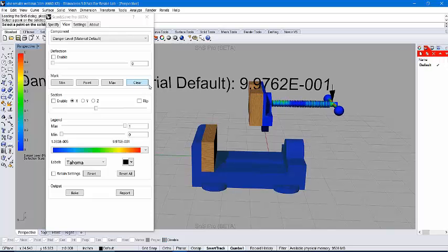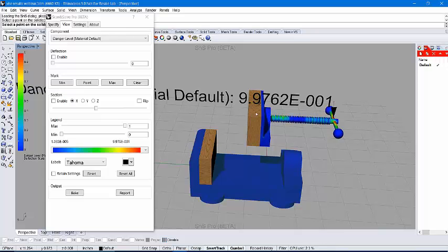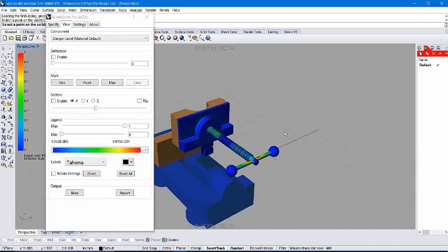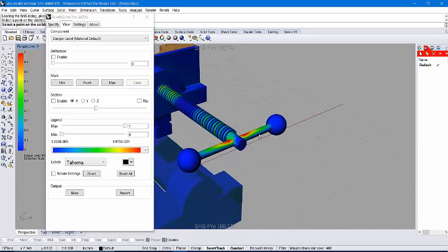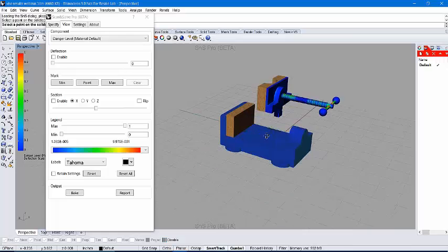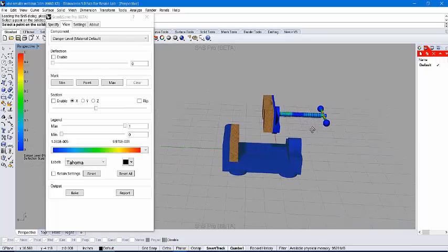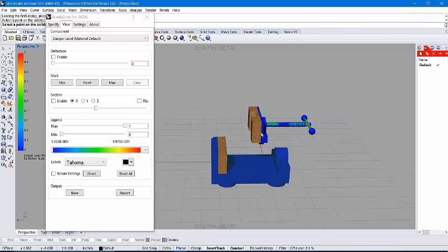So this is cutting it pretty close. If I was actually going to be applying these loads, I would probably want to change my geometry so that the cross-section in the shaft of the handle is slightly thicker. By increasing the cross-sectional area, I should be able to decrease the danger level, allowing for a safer use of the vise.